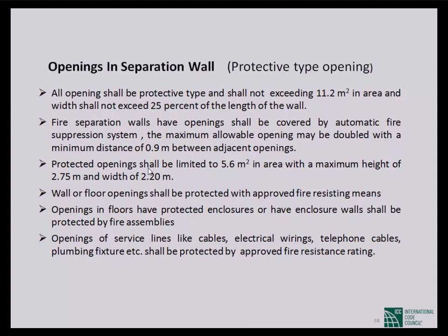Then it is protected by enclosure walls or some other means, or protective opening assemblies. That is the big opening. If it is a service line like electrical or plumbing, then normally in NFPA it is called a penetration. But BNBC does not say it is a penetration. BNBC uses it as opening, but it is a small opening.